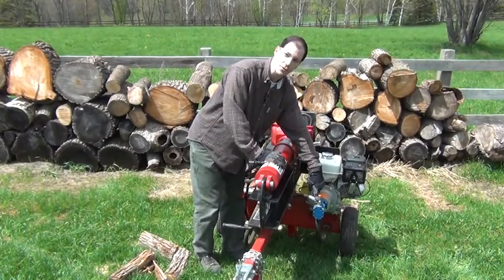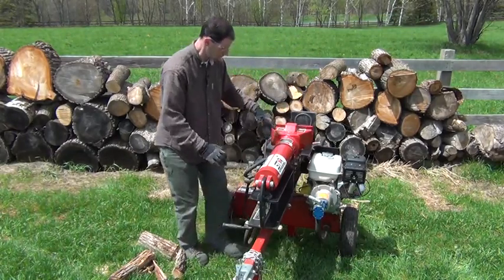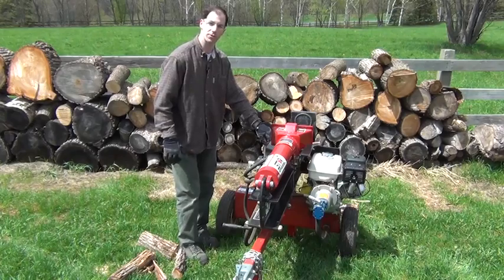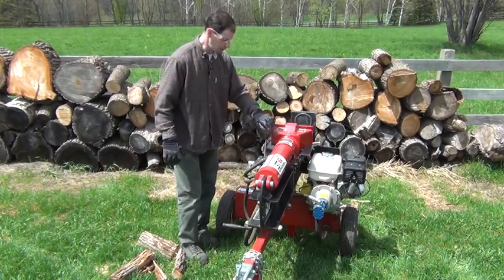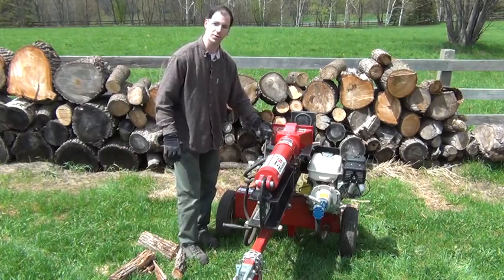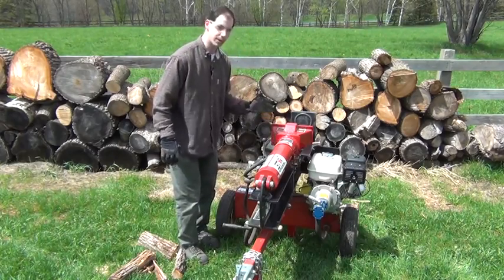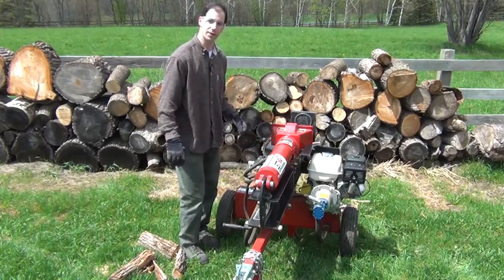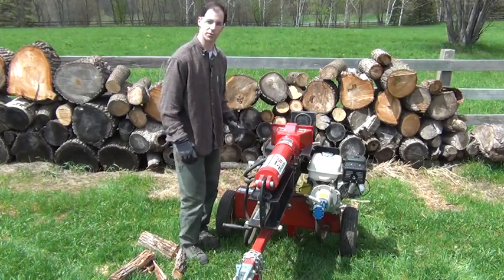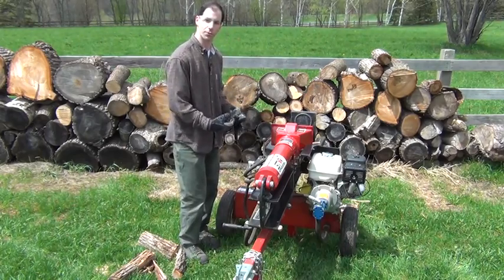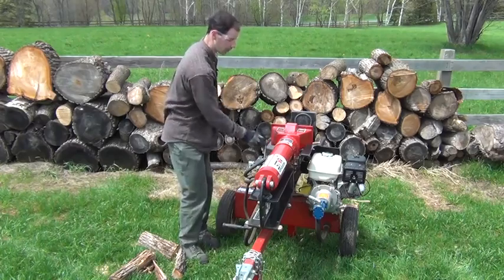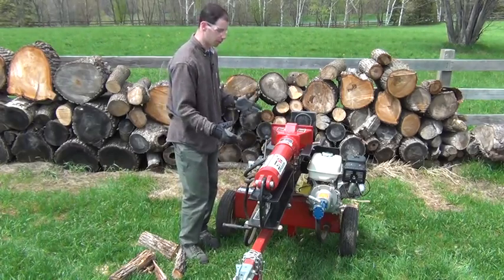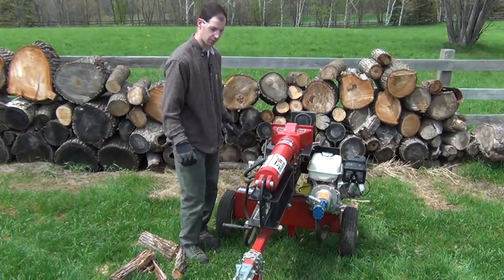The high pressure fluid coming out of the hydraulic pump goes over here to a four-way, three-position valve. It's lever operated. You'll notice that it is spring return to center, but you'll notice that I did hold it in position and it returned by itself, and so it is detent operated in the return position, and then when the pressure starts to build on the return, it pops this back to its center position. And that is what controls the flow going one direction or the other.